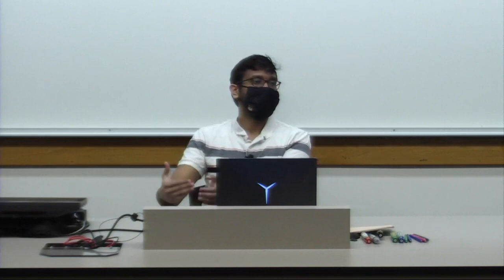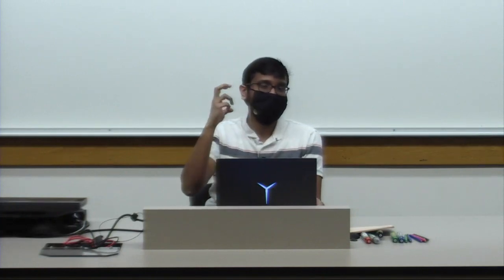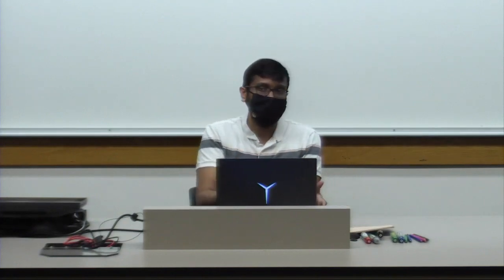So you can write statements along the lines of: wait 5 nanoseconds, then drive this input. Wait 10 nanoseconds, read the result, then drive this new input, things like that. So you have a lot of flexibility when it comes to test benches. I won't go into exactly how to run it, but if you look in the folder, there's something called a run file, which contains the command lines you need to put into your terminal to run this, or you can even source that file directly.